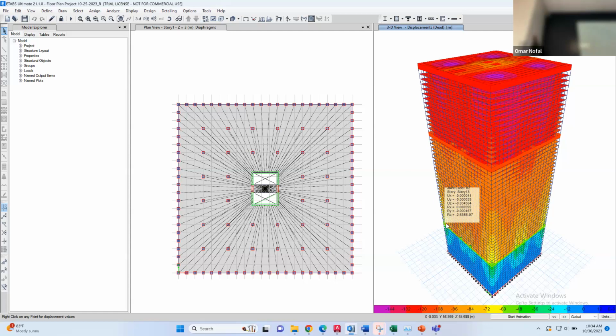shear. So you guys have multiple models, right? Like around 10 models with different beam parameters, different spacing, or so. What I want you to get in terms of results for each model is very important. Number one, because we are doing a parametric study, I want to know what is the difference in the base shear.